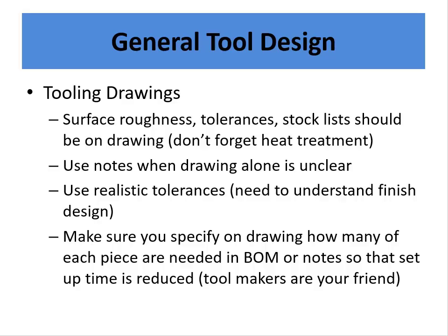And this is a general thing, but it's specific in that you need to make sure you specify what you need. So sometimes on a print, if it's supposed to be an entire data package, you're going to have to include your bill of material and your notes for the tool makers or whoever are actually making your tools.